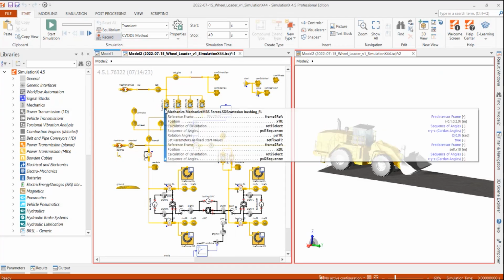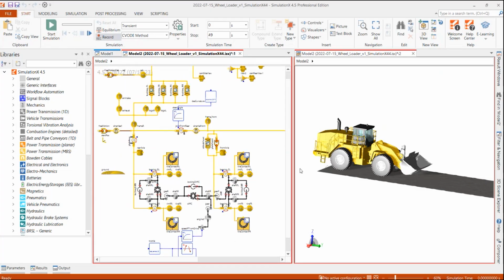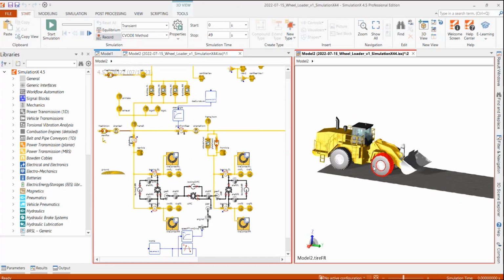The vibration originates when the wheels interact with the uneven ground. It is transferred from the ground to the wheels, through the bearings and axle, into the frame, and finally through the bushings to the cabin. The bushings, therefore, play an important role in controlling how much vibration reaches the cabin.